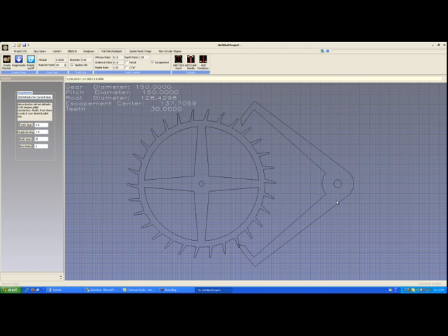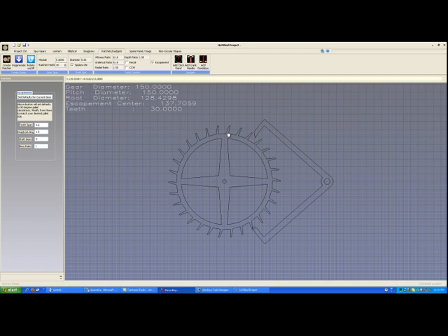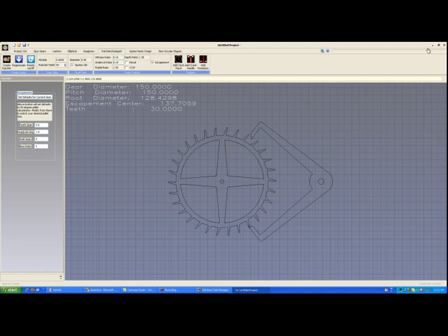This large circular area around the shaft is our boss ratio. Basically, a boss ratio of 3 means that the area here should be 3 times what the diameter of that center shaft is. So we can see if I lower the ratio to 1, that we now have a very narrow rounded part here, so a lot weaker. So use a boss ratio which gives you a circular area that's strong enough to hold your pawl, and that's basically the only thing that you're going to have to worry about in that regard.